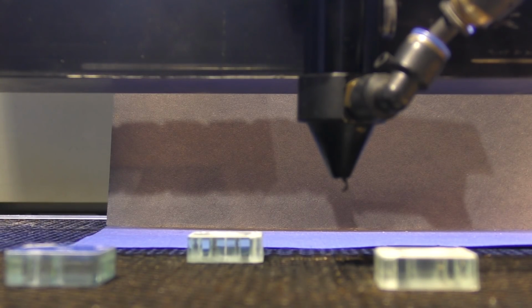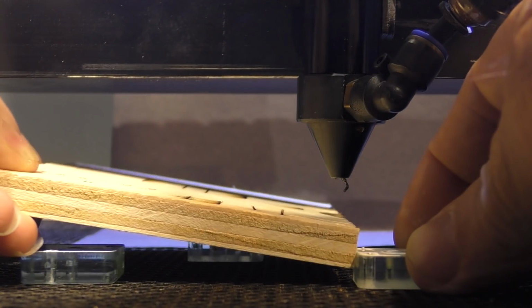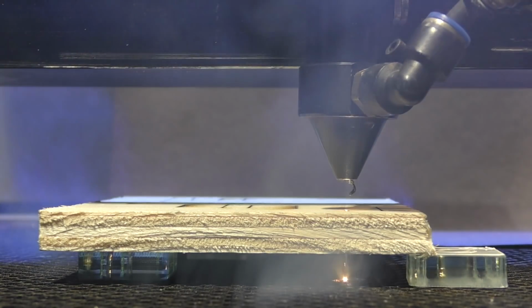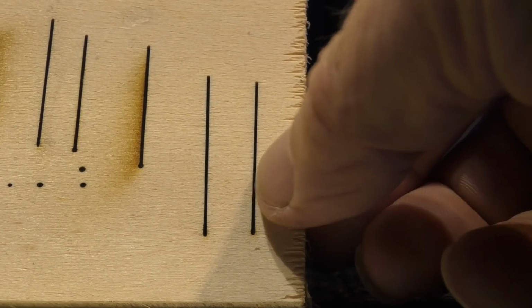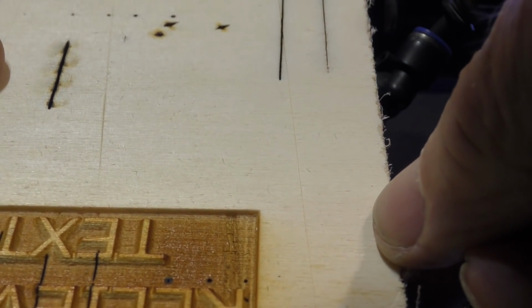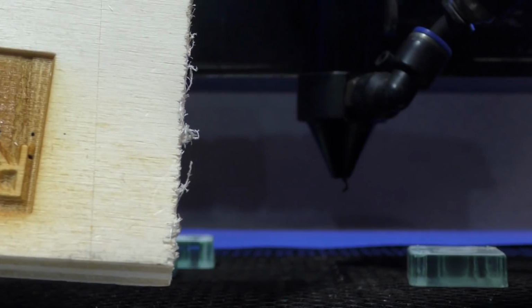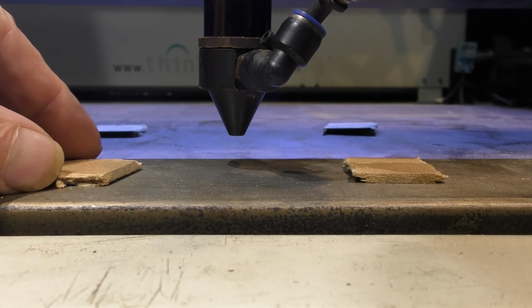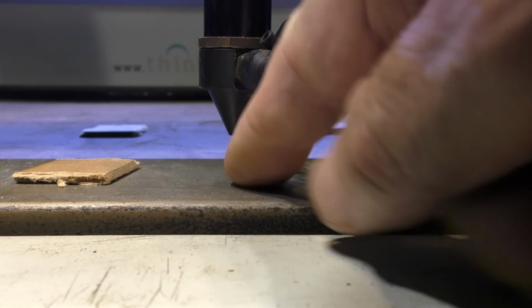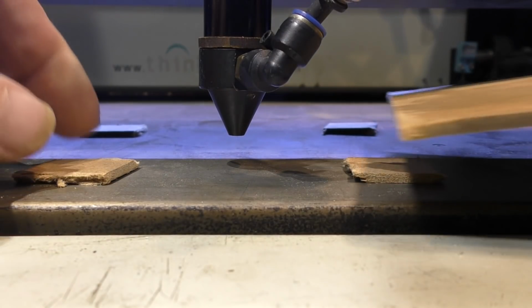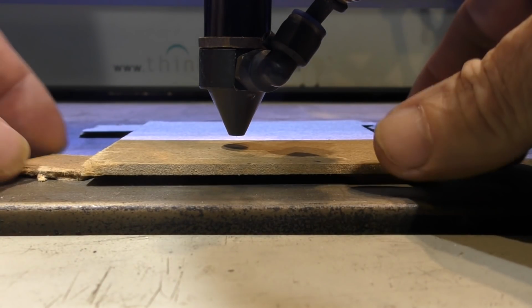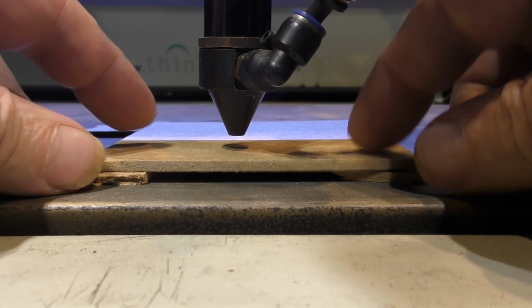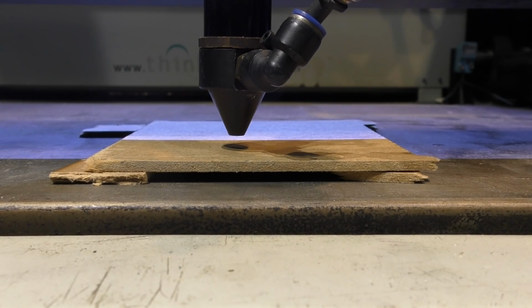So I'm going to take that down to about 7. We'll run another cut beside it so that we can compare them. And now we've got a cut which is much the same on the top as it is on the bottom. And that means we've basically got a parallel cut through which the air can flow and it does not get choked. I've got my solid table on now, which is a piece of nice cold steel, and I've got some 3mm spacers and some 3mm HDF. Now I'm going to do the same thing that I've just been doing. We're going to run a line away from the camera.